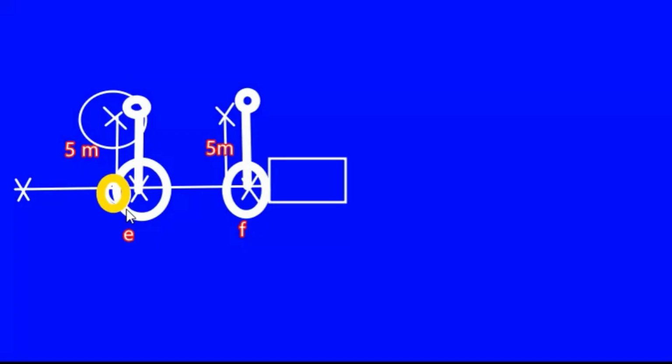I'll just change the color over here, right? And then when you get this line absolutely straight after putting the cross staff over here, you look towards this side, that is towards the side of the other ranging rod which has been placed at 5 meters from the cross staff, and you keep on producing this line in such a way that it crosses over the building, right? Now again select any 2 points on this particular line that you have already ranged.